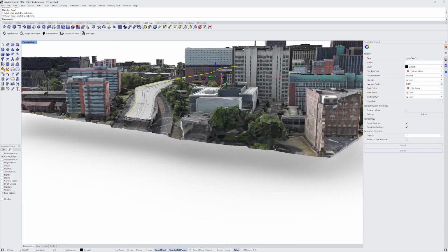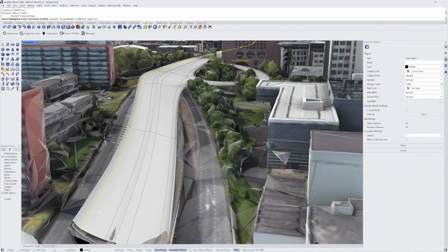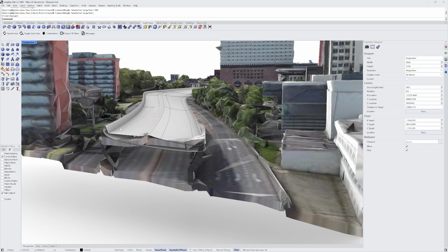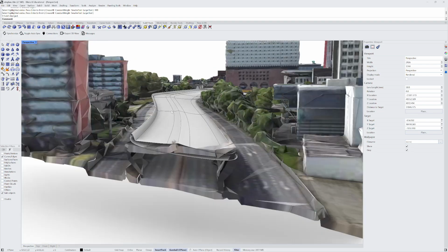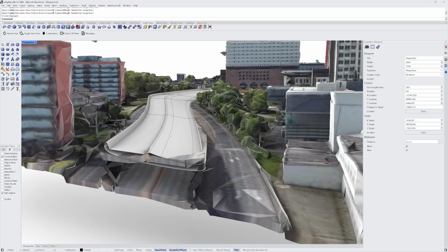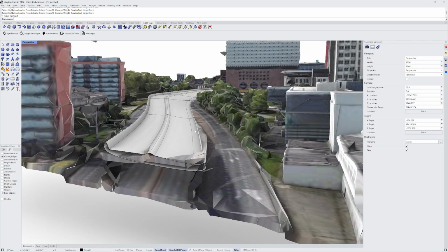Or another way that I can get a hard edge is by creasing. So I can go to the crease tool, which is just up here, and if I do it at 100%, that's going to be a perfect 90-degree angle, and it's going to really harden that edge. I can do the same with this one, at 100%. If I select that edge and type the command 100, it's just going to start hardening that surface, hardening the edges where they meet. I can run the command again, 100, and it's just going to start doing that.